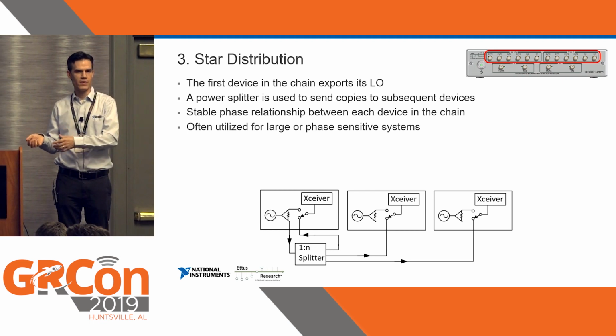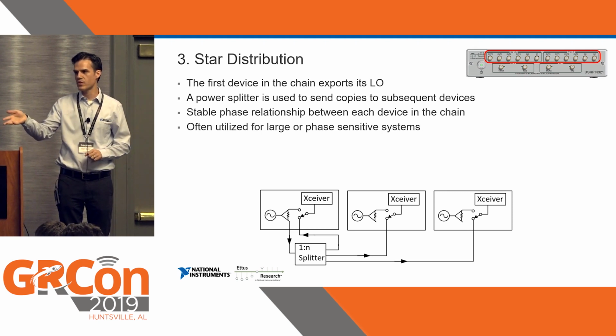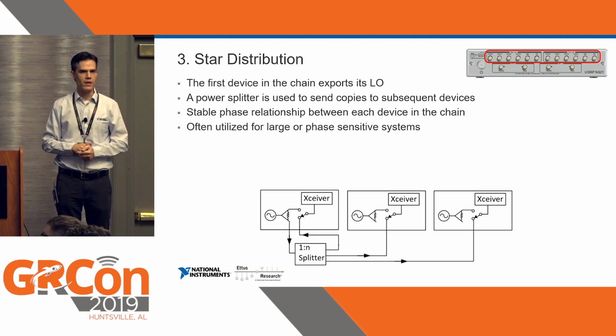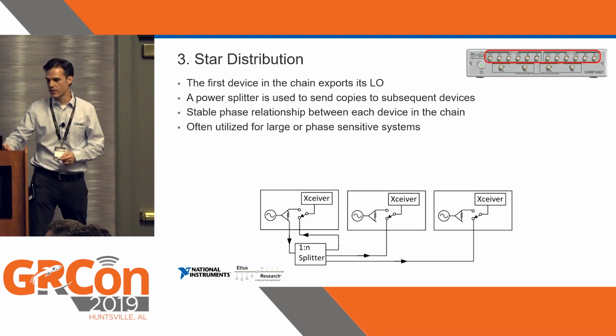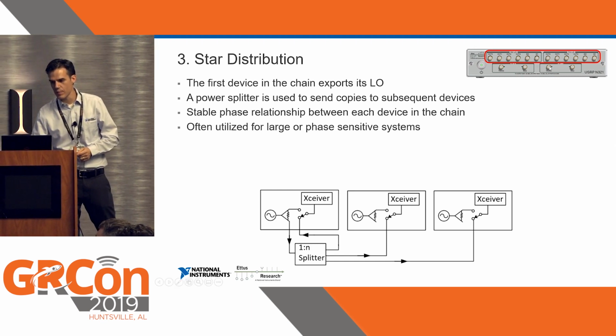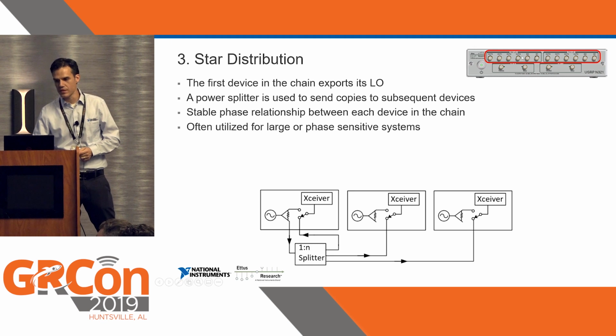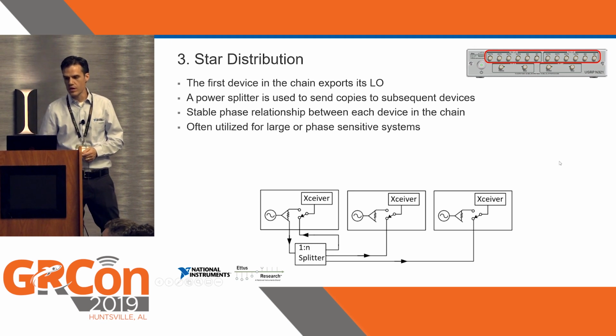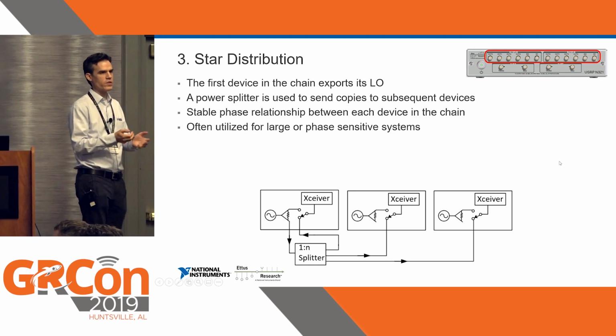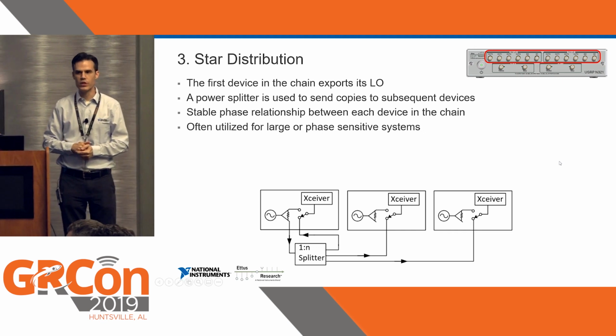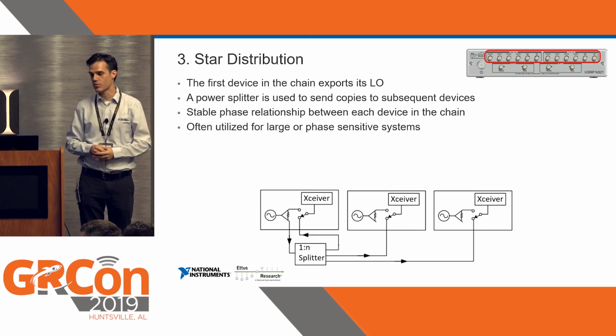And this is something that my colleague Brian Avenell built into the new N320 and N321 products that we make at National Instruments. In fact, all these SMAs that you see across the top up here on the top right, it's a whole ton of SMAs in the N321. And what those are is a big splitter network for distributing LOs in a really cool way. Turns out this works extremely well.